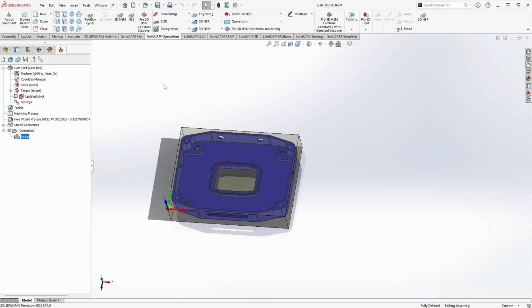In this video, we're going to cover facing operations. Now, when we say facemill operations, we're not actually referring to the type of tool you might be using, facemill, shell mill. We're actually talking more about the act of physically facing the part, removing all of the material from the top surface of the part. And that distinction will make a little more sense when we get through how these toolpaths are actually generated and what the toolpath is looking at.